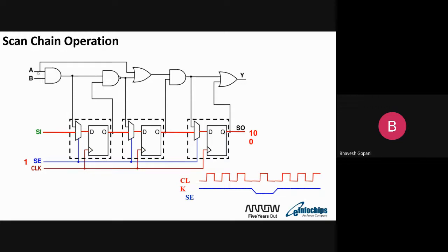But suppose my gate is working fine when I apply the stuck-at vectors to it. Does that mean there is no issue with this gate? No, right? There could still be an issue with this gate. A stuck-at pass doesn't assure that my gate is working fine.